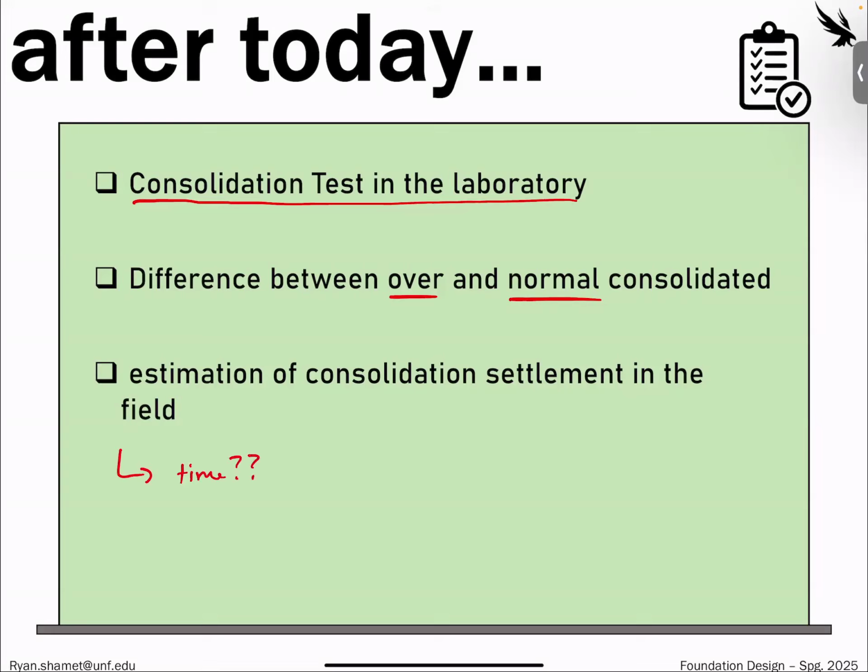That's a huge thing because like the water balloon, depending on how much you press on it, it could take just 5 minutes, it could take an hour. And from a construction standpoint, that could translate to 2 years or it could take 1,000 years. And one of them is probably more crucial, right? If we're going to see settlement of this building in 1,000 years, maybe we don't care as much as if it is going to settle in the next 5 years. So the time aspect is also important in consolidation.